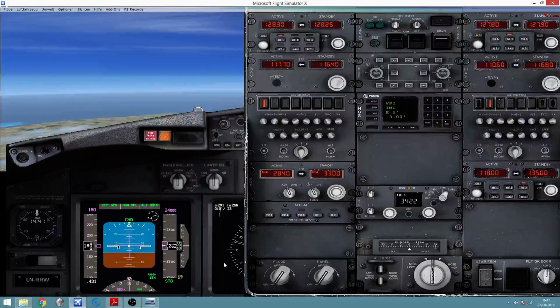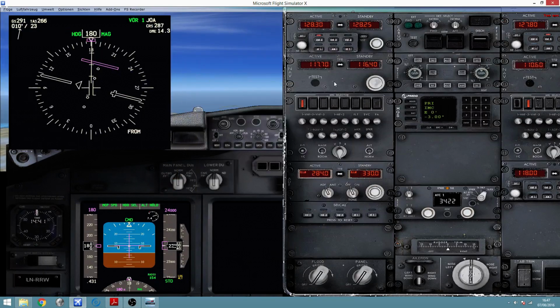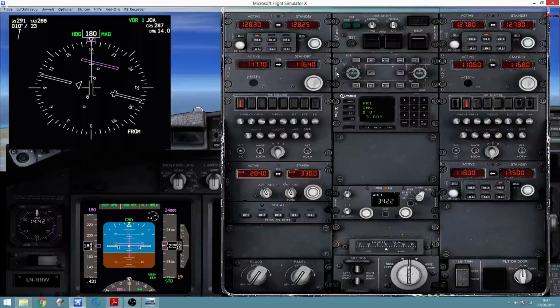All right, so here on the navigation display I will be reading the different VOR indications of only the VOR number 1, which is this one. This one is for VOR number 2. This indication is going to show only VOR number 1 and is going to show only the active VOR number 1. How do I change from standby to active? By pressing this transfer button. All right, you've seen now that I've changed from the VOR of Palma to the VOR of Pollença.